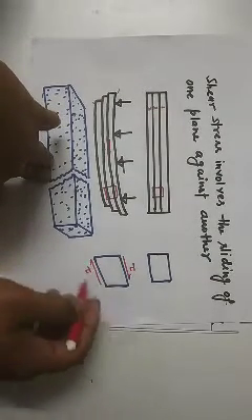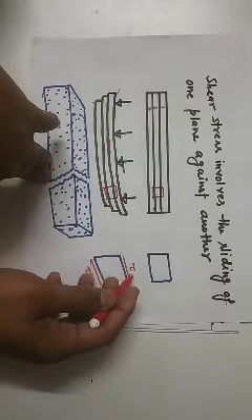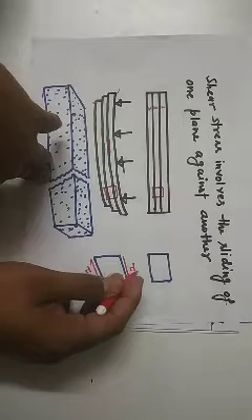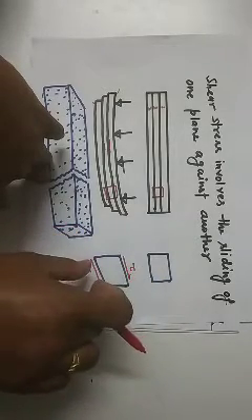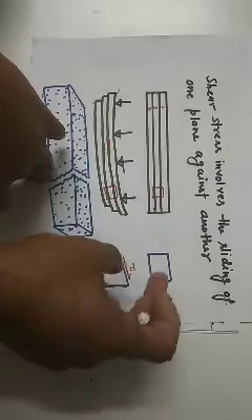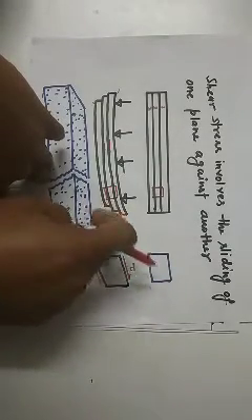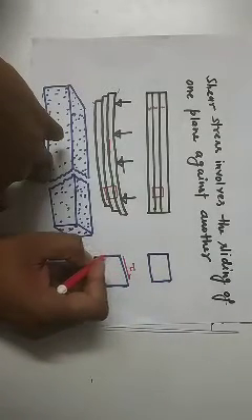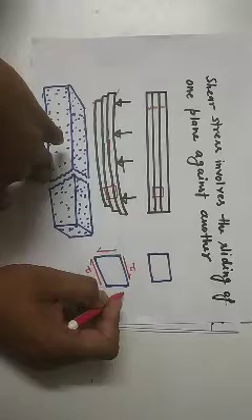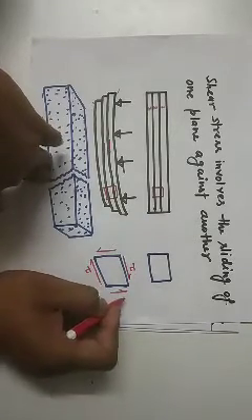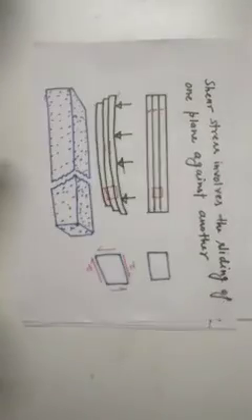Now we know from the concept of static equilibrium that if two shear stresses are set up in the beam, these shear stresses will try to rotate this segment in the clockwise direction. To oppose this clockwise rotation, there will be an opposing rotation set up by the beam itself, and this shear stress is known as complementary shear stress. We have already studied it when studying stress analysis.